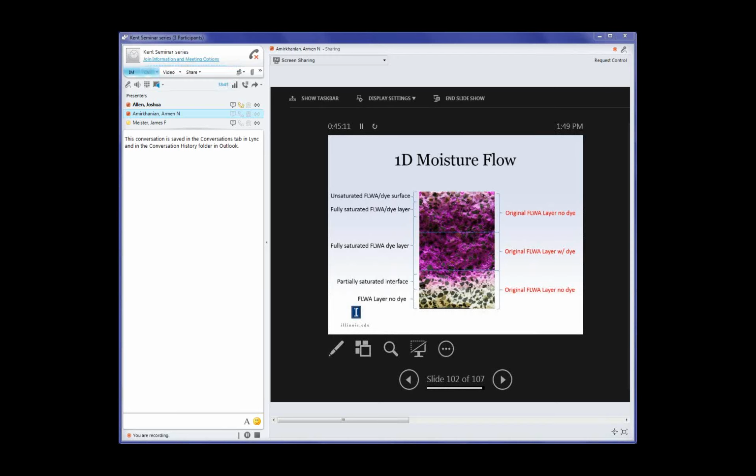So we can see the bottom layer, some of the dye has creeped down, which would be expected because these were cast wet on wet. So there's already some bleed water that's moving before the concrete is set. But this down here is perfectly white. There's no dye, nothing. The top was the drying surface. At the top, this was originally all white, but all the water has gone up through and taken the UV dye with it and evaporated out.